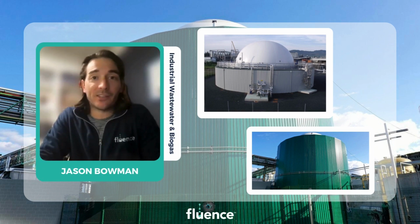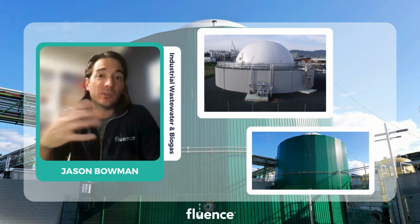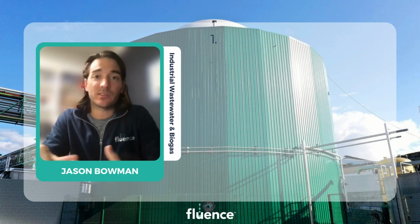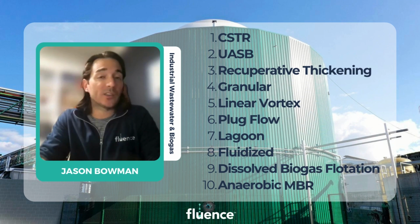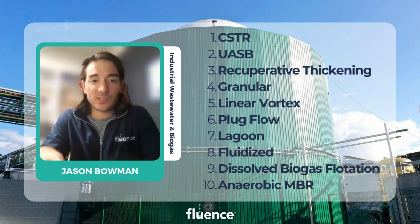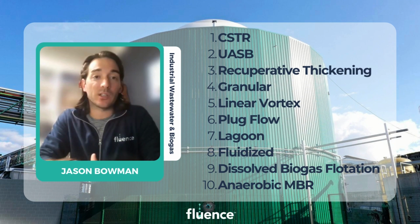All right, so we're here to talk about digesters. Let's jump right in. As I mentioned, there's at least 10 concepts on a global basis that I'm familiar with. Today, we're really going to focus on 3, but I'm going to give you a list of all the options that I'm aware of. So let's start. You have a CSTR process, that's a complete mixed reactor. You have a UASB process. You have recuperative thickening. We're going to talk about that in this presentation. We have granular. We'll also talk about that in this presentation. Then you have linear vortex, you have plug flow, you have lagoon, you have fluidized bed reactors, and the list goes on and on. So why are there so many different styles?